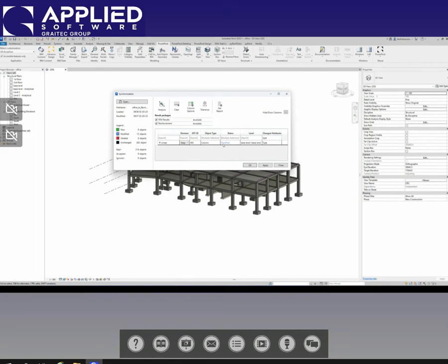This is the same column that, if you remember, I modified in Advanced Design. If you want to see more detail, click here, and in the parameters, it's going to show you what's happening to that column. It tells me that it was a 60 centimeter column, and now in the new import, it has been changed to 80 centimeters. As you see, it's automatically detecting my changes.